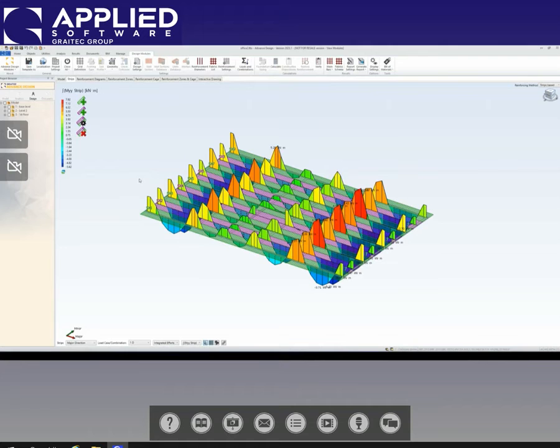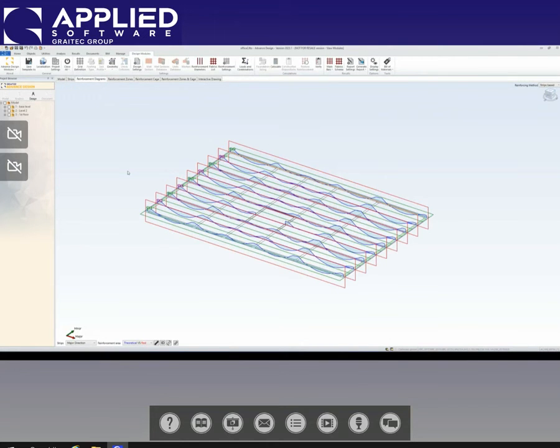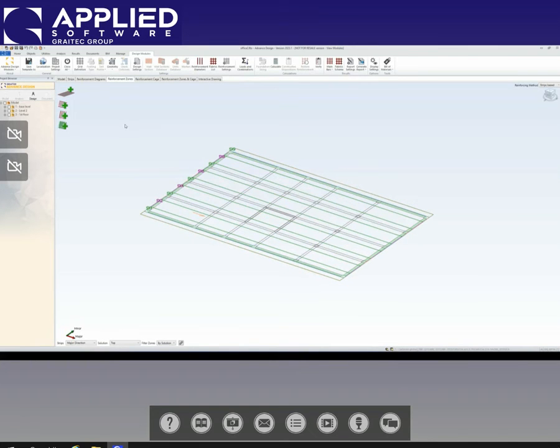So here we can see the reinforcement diagram, the required, theoretical and real ones. You can check your reinforcement zones. If you want to define extra zones for your reinforcement, you can define them from here. By default, it's going to be covering all of the slab, but using this tool, you can actually add extra layers, etc.